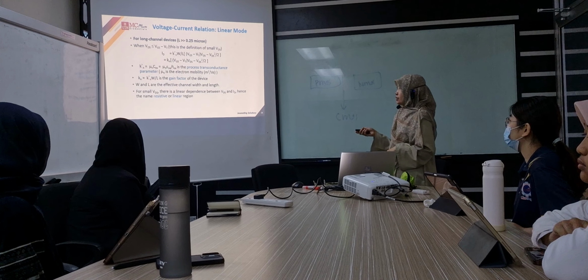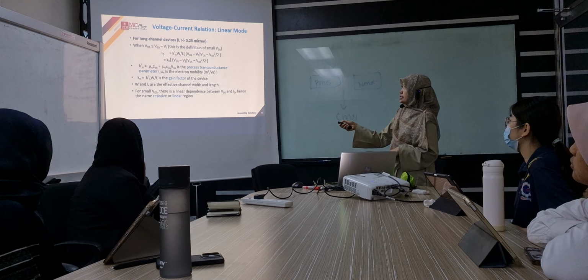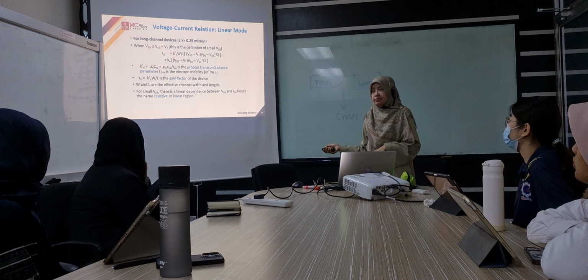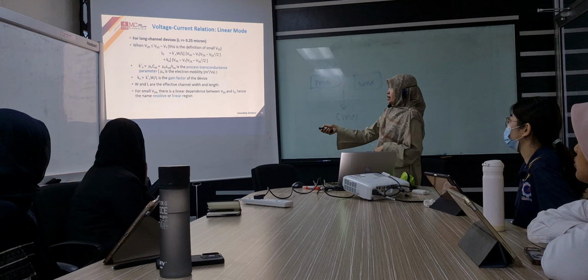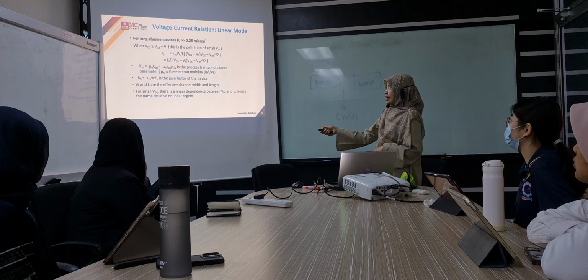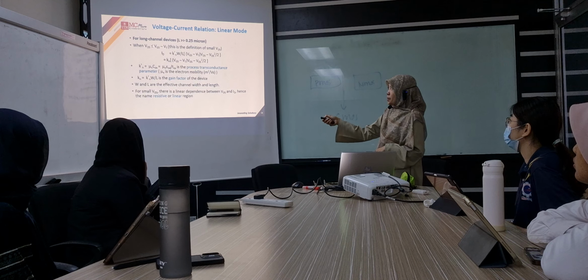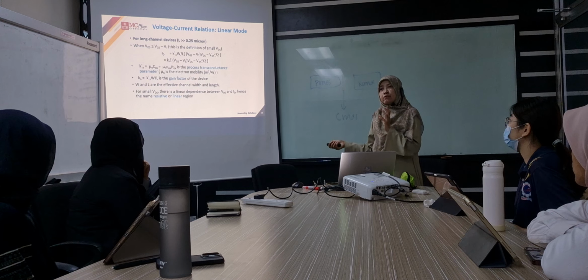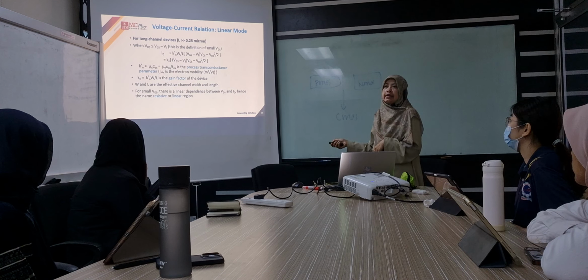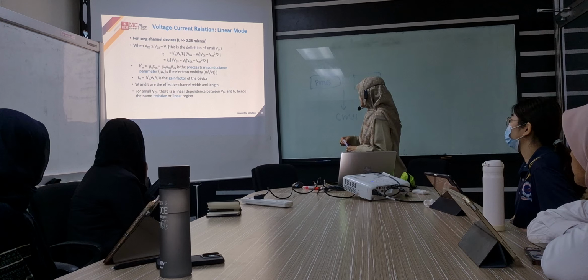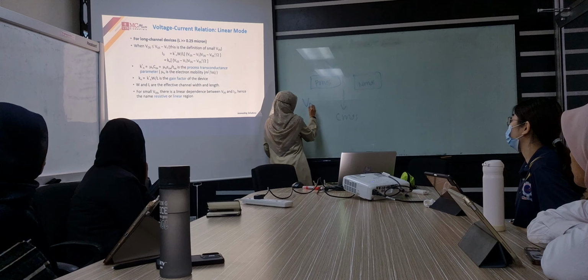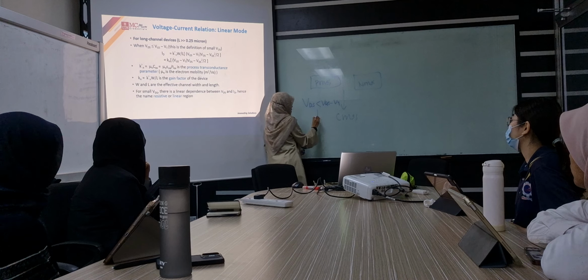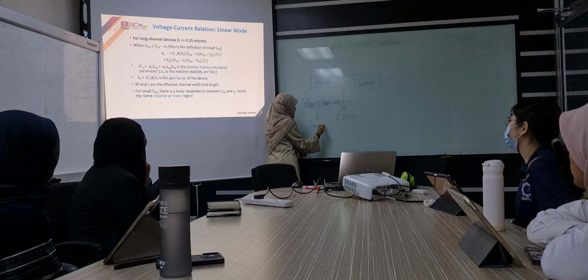For the long channel, we will use these equations to design MOSFET in terms of current-voltage characteristics. Okay, so this is the linear region. If VDS is smaller than VGS minus VT, then it's working in the linear region.